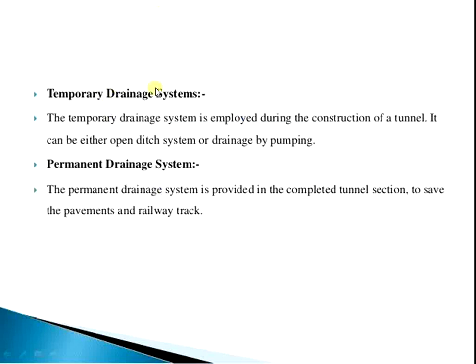Next is the temporary drainage system. The temporary drainage system is employed during the construction of the tunnel, and it can be either an open ditch system or drainage by pumping. We have to provide either an open ditch system or drainage by pumping.